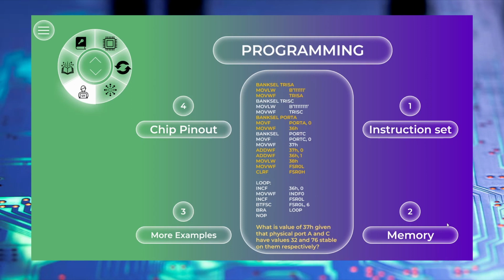That is very important to know, because for you to make use of these registers that we discussed earlier, you need to switch to the right bank first. Looking at this code, we can see that we have BANKSEL TRISC. With this directive BANKSEL, we are first switching to the bank that the register TRISC is in, before we can make use of the TRISC register.